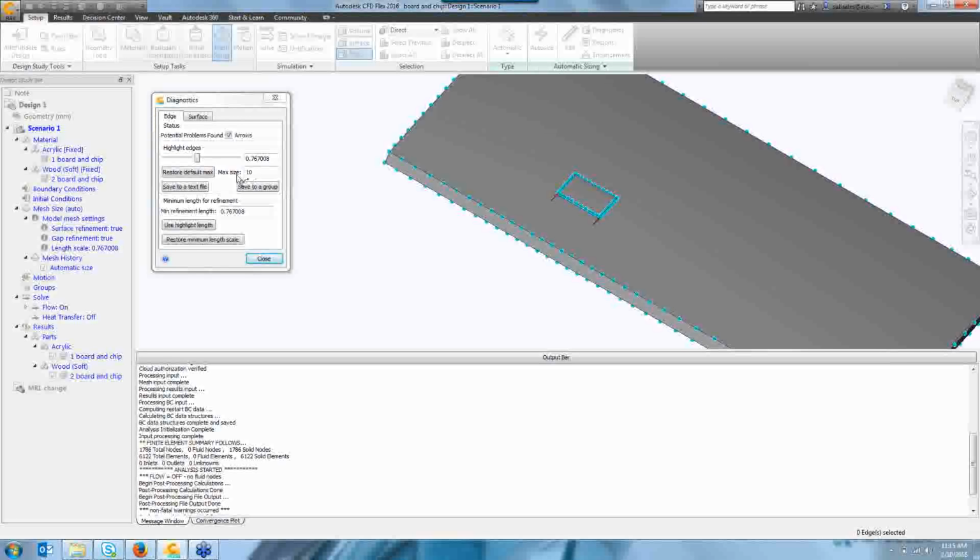The beginning of volume meshing is where we put in our enhancement layers for all of our wetted surfaces. So if you fail right in the beginning of volume meshing, or it hangs in volume meshing, typically that means that we have a problem with our enhancement layers, either overlapping or not being able to wrap around some kind of corner.